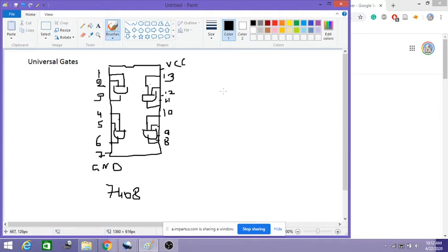Now what I want to tell is, previously we had written one circuit, for example something like this. So we have used one NOT gate somewhere here. I have connected these inputs in this way, then I have performed the OR operation here. So it means I have to use 3 different ICs, but I am not utilizing all the 3 ICs efficiently.